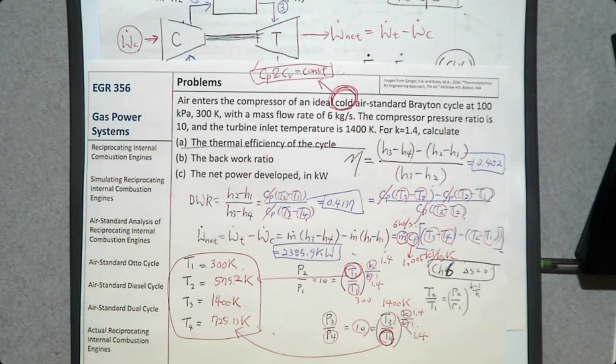On the other hand, if the temperature of the heat source is very high, like a nuclear reactor, it is more recommended to use Brayton cycle. So presently, most commercial nuclear reactors are using water, Rankine cycle. But most advanced nuclear reactors that people are researching right now, they are using Brayton cycle.